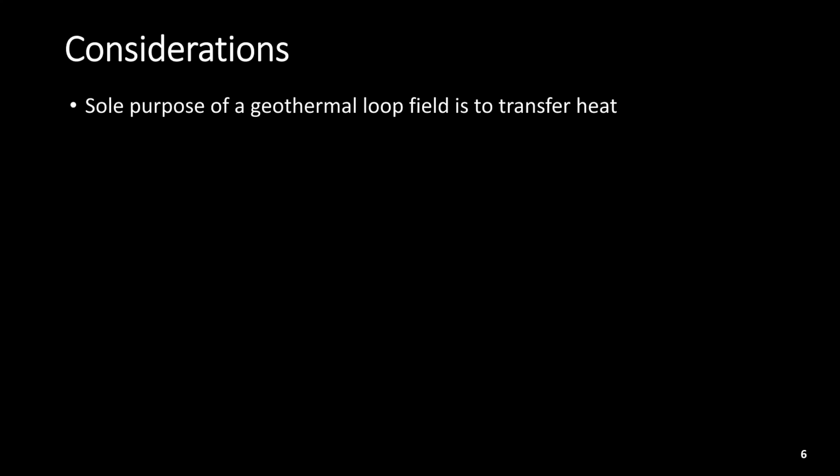The considerations when looking at a loop field design. First and foremost, you have to remember the sole purpose of the loop field is to transfer heat. Temperature is the main driver, not flow rate. And I wish I had a nickel for every engineered geothermal loop field I saw that engineers felt compelled to put a balance valve on circuits. And it's one of my pet peeves, and that's what has driven me to talk about this subject today.